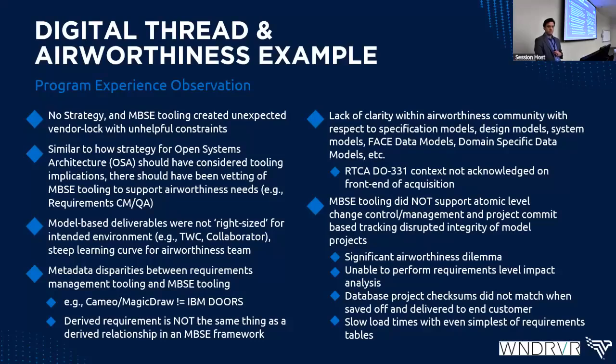In NIST world, which is sort of what Cameo based its relationship off of, it has a relationship to a parent. In RTCA world, or safety framework world, a driver requirement does not have a parent on purpose, and it gets justified. So when I'm synchronizing snapshots via Data Hub, which, by the way, introduces other complications with respect to things like qualified tooling that you have to deal with in the airworthiness community, it doesn't work. And even when it does get synchronized, there are bugs that are induced.